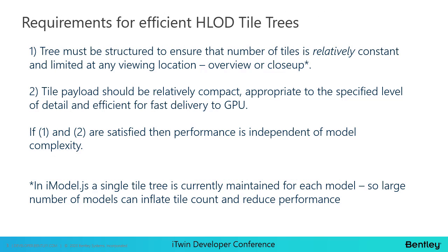Now for a HLOD tile tree to work efficiently, there are two basic requirements. First, the tree must be structured to ensure that the number of tiles for any given view is limited and relatively constant. Two, the payloads for each tile should be compact and organized well so that they can be efficiently delivered to the GPU.